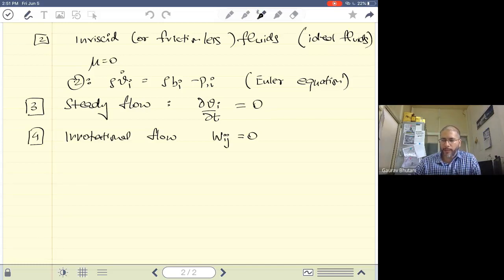If you remember, we discussed that W is a skew symmetric tensor, so it has only three distinct components. From these three distinct components, we can create a vector, which we call the axial or the dual vector of W, which was named omega, called the vorticity vector.